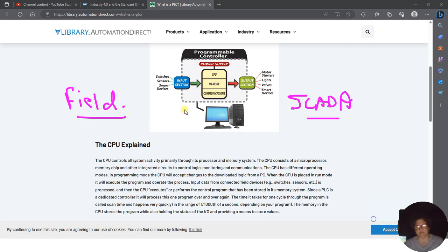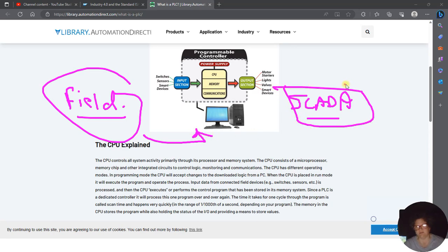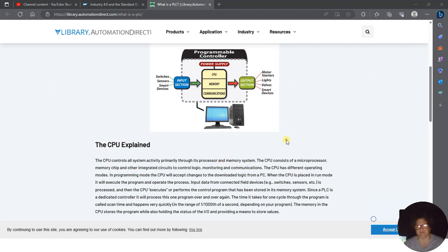These two need to be in two different locations so that these can update and be used in here, but this can update and be picked up by the ERP or MES. And that way it's a standalone and it doesn't affect that side. So that's why I brought it up in relation to Internet of Things and ISA95, because you have a direct link from the PLC to ISA95 data.